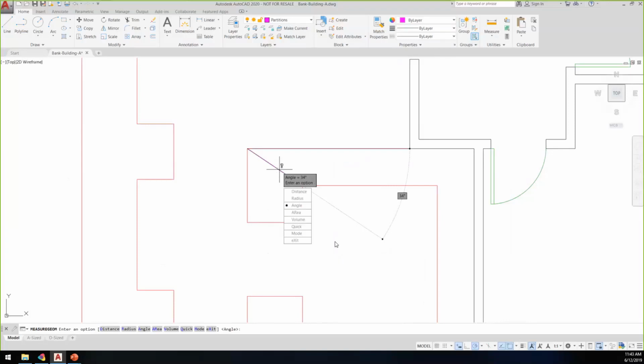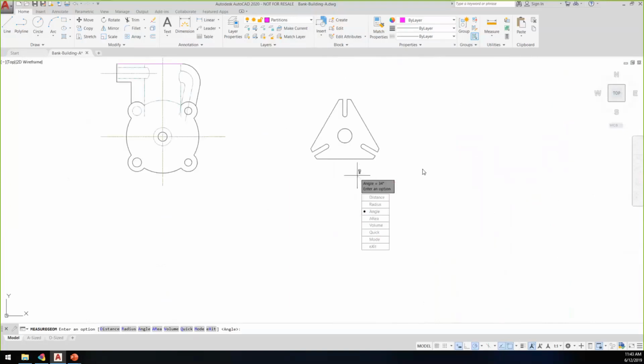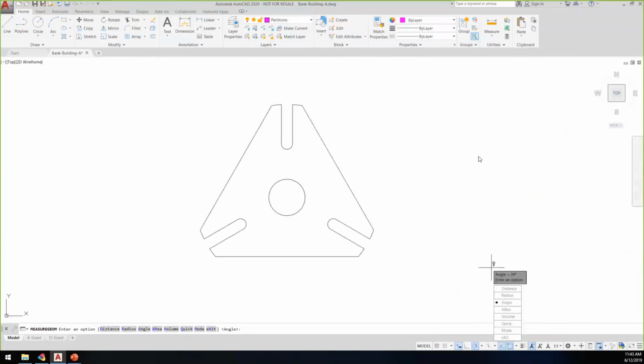Now let's go back and we can get the area option. So I'll show you how to get the area. So first of all, go in here and choose area, and then select that object. It'll ask me, I can either pick the different points and choose the area of that object.